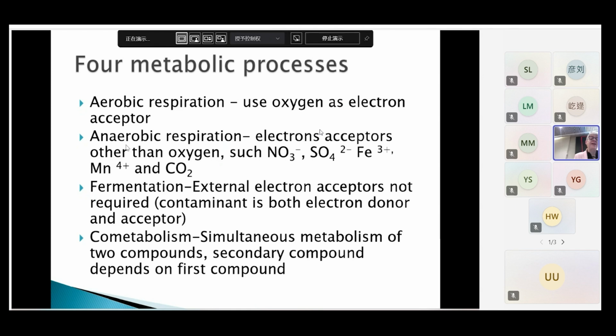So things like heavy metals can be fixed this way. But organics don't work quite as well, so you might have to add some other types of things. So pozzolans are also used for inorganic materials. Lime is also used for inorganic. And if you're going to use organic, you might have to do some modification of these different types of cements to organically modify them to have better compatibility with the hydrocarbons.